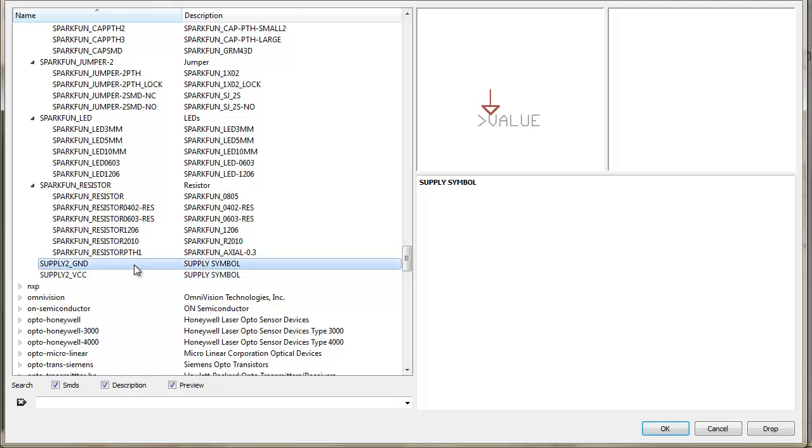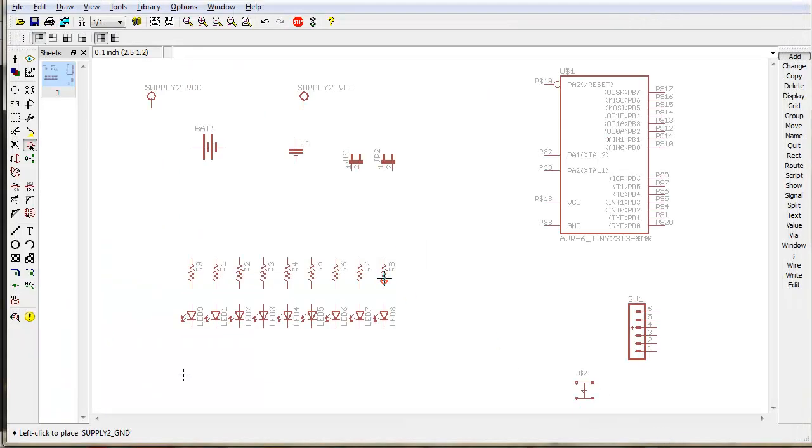Okay, next we're going to add some grounds, and these basically just tell Eagle what we're connecting to the ground, and later on to actually draw onto the board. We have a few different grounds here. Pop them here, and another battery, one coupling capacitor, and one each for the 2 jumpers. And that is it at the moment.